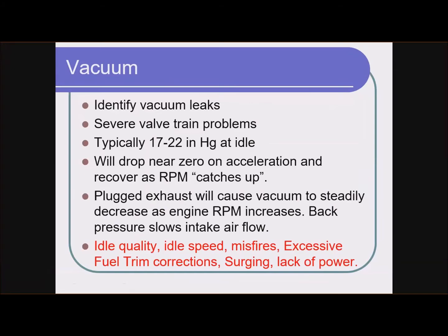On some vehicles, particularly vehicles that use a speed density system, where it does not use a mass airflow sensor but uses manifold vacuum to determine fuel control, creating a vacuum leak is no different than opening the throttle. It just makes the idle speed go up.